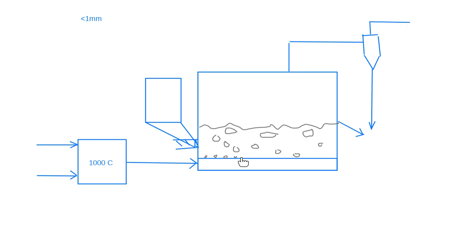And so within a few millimeters, that hot gas can go from 1000 degrees to whatever temperature you're operating your fluidized bed at. Let's say we're operating this fluidized bed at 110 degrees C. So it will very quickly go from that 1000 degrees C to 110 degrees C, and all of that energy,